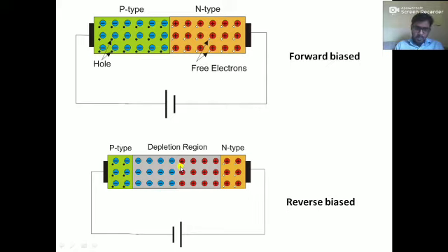So this electron collides with an atom nearer to this area, and this atom ejects one more electron, and that electron has some kinetic energy and moves with very high acceleration, and that electron also collides with the nearest atom and ejects one more electron. So the electrons collide with the nearest atoms, and each produces one more electron ejected from the silicon atom. This kind of effect is called the avalanche effect, and because of the collisions they produce and generate heat.